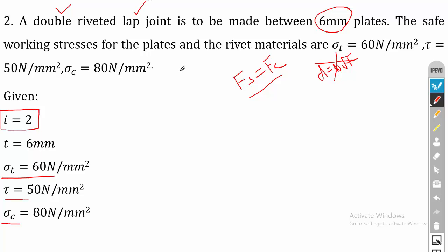Okay, so remember that for a lap joint we don't need to calculate the cover plate length. We can directly start from step number 2. So just remember this design procedure. Refer to the data book pages 7.124, 125 and 126 for the equations. All these equations are available in the data book. Don't memorize this. Just remember the procedure. Use the equations from the data book. So the design of rivet joints will be very simple for you.